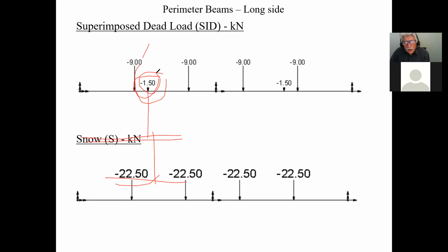And when we're going to be designing the girts, if I was doing this as a real project, once I've designed the girts, I would definitely know what the weight of this girt is. And then from the weight, I would be able to calculate what is the amount of force that's being applied right in the center. And then I can go back and check if this assumed value was okay. In other words, did I overestimate the dead load from these girts? And if I didn't, I would go modify this value in my ADA and see if it has a real bearing on my results. So this is just to compensate.